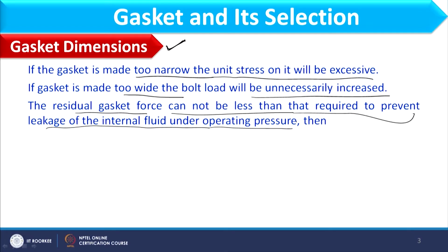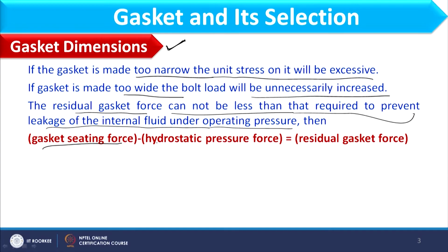Residual gasket force means when the gasket stress will act. When does gasket stress act? When I have the seating stress minus the stress generated due to pressure. So, what would be the residual gasket force? That will be considered as the minimum seating force minus the force due to the operating pressure. So, it will be written as gasket seating force minus hydrostatic pressure force equal to residual gasket force.